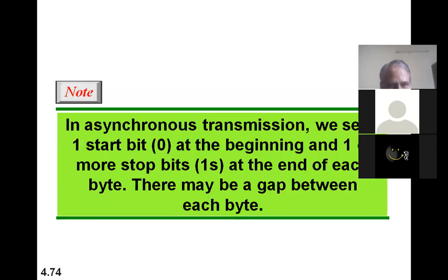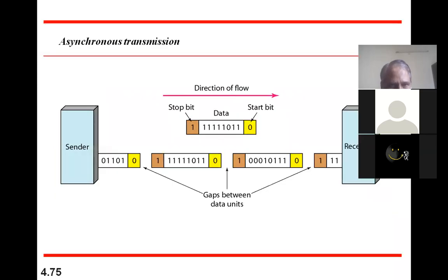Now there are three types of serial communication: asynchronous, synchronous, and isochronous. In asynchronous communication, the data is transmitted asynchronously. That means anytime it can start, and after sending a certain number of bits, it stops. Because the data is not continuously coming, the receiver is not always synchronized.